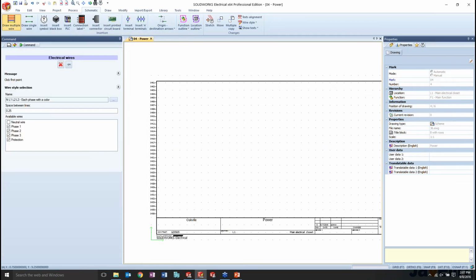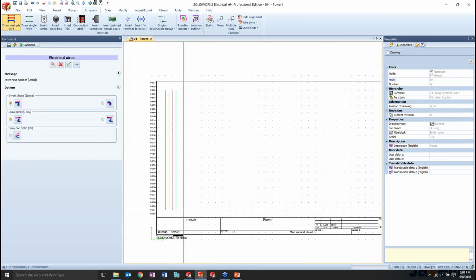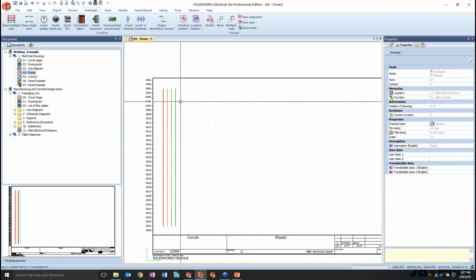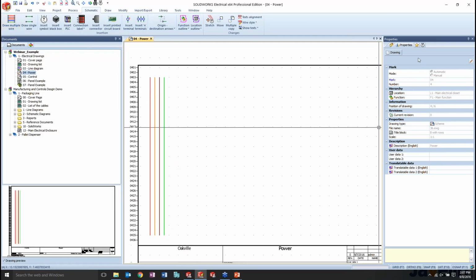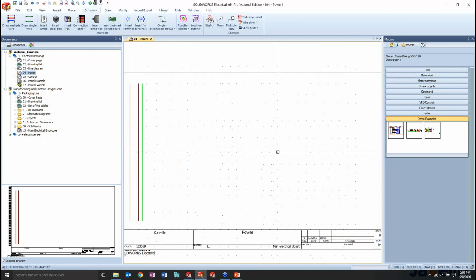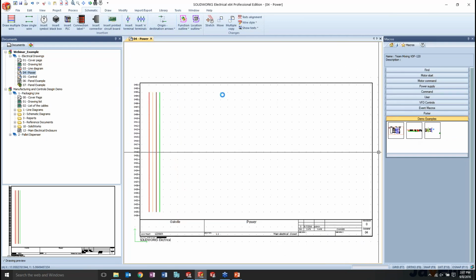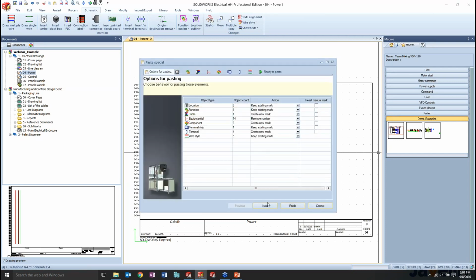The first thing I'll do is put some power lines here to connect to the power. Maybe I'll just start there and go to a macro, so I don't waste time designing today. Go to my macros and maybe drag and drop a motor control section. You get some options when you drag and drop from your macros, which is a great thing to do.